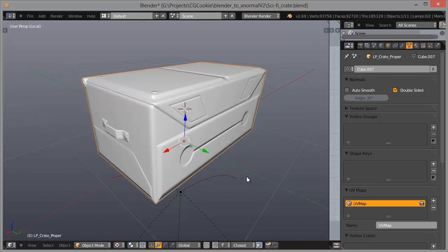So things to keep in mind while doing this is always triangulate your mesh before creating the cage and before doing the bake. That's something you always want to do, or you're almost certain to get some errors. Remember to keep your naming convention right, in case someone else picks up your scene. And remember that if you have a hard edge in your low poly, you need to have a split in your UVs, or else you will get seams.